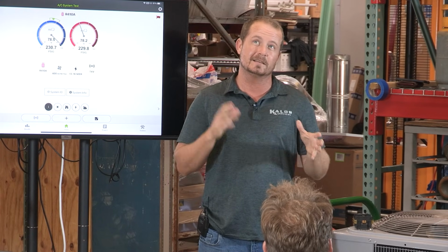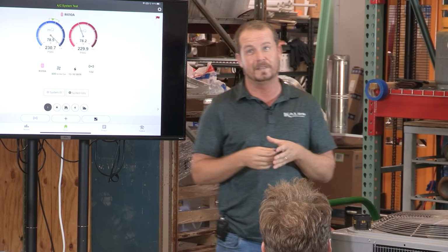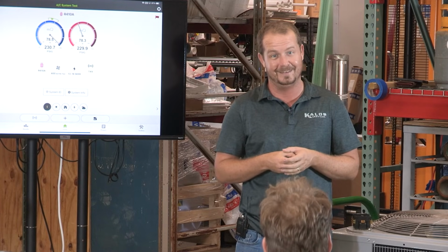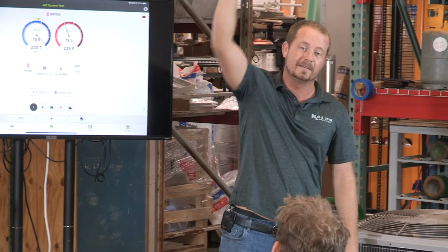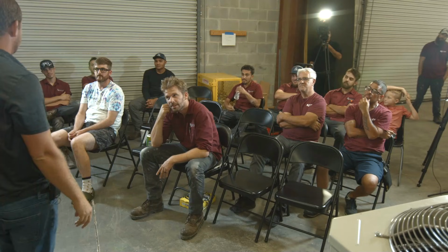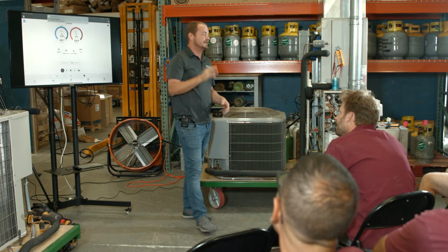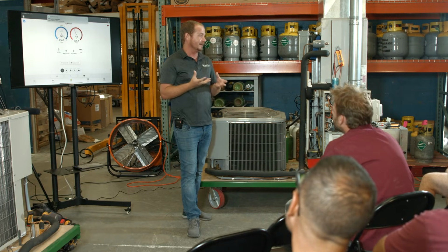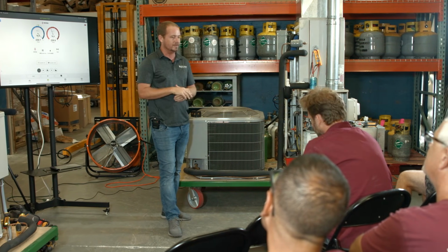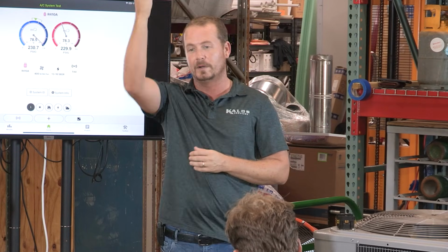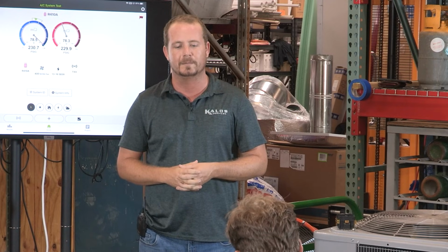So you'd be like, hey, this laundry room seems like it's putting out way too much air. So I'm going to make the hole on the inside real small. And then you take the grill down, bend it, and force it way up in the duct. You know why you forced it way up in the duct? The inspector don't see it. No, that might have been a reason. No, the reason is because if you put it right down by the vent, it would make a lot of noise because it would come through at high velocity. It would hit just a portion of the grill, and it would make a lot of noise. So you shove it way up in there so it has time to become more laminar and fill the duct before it comes out.